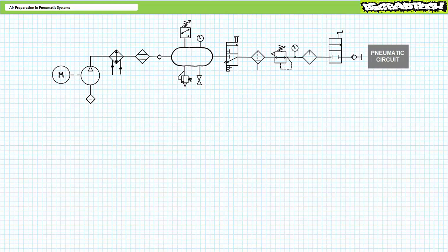The pressure switch's set point is ordinarily higher than the regulator's, such that the regulator allows for brief sips of the greater stored energy in the receiver, thereby keeping pressure inside the pneumatic circuit inside a given range. This is why there are often two pressure gauges within a compressor circuit as illustrated in this diagram, one in the receiver and one in the FRL.